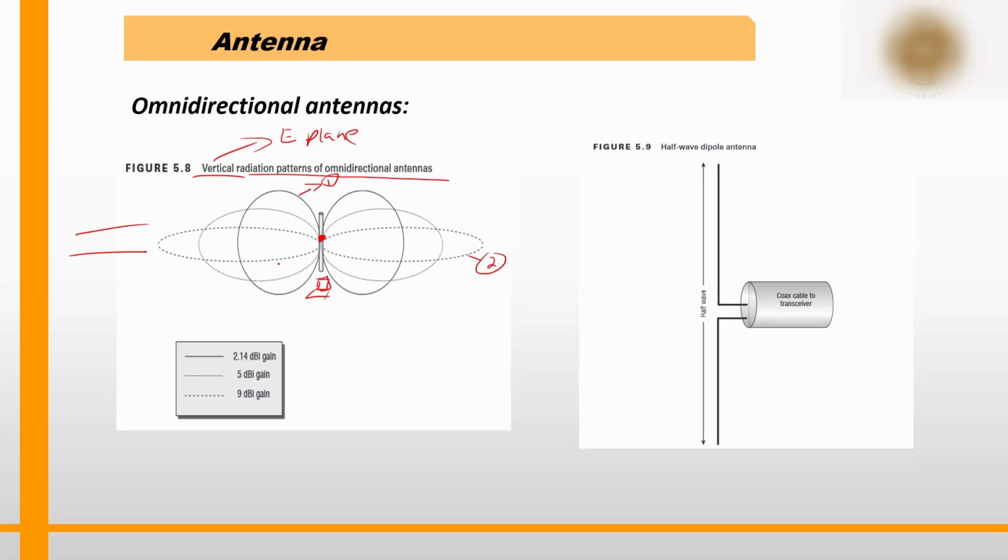So when you increase the power, you can focus. That is one correct answer. The second answer is you need to use that particular antenna. Whether you are using omnidirectional, isotropic, that also will matter. It is not only the power. Power is how much distance it can travel. But the shape of the antenna, the orientation, the polarization, that's what makes the lobe look like this. This is one lobe.